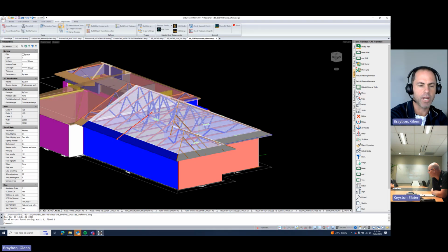Yeah. 100. We are definitely trying to develop the ability of using the light gauge stud section in its strong axis as a beam. Obviously, we're starting with those frame headers. We're doing some testing on that, where we're putting the C90 section in as a wall frame above the opening, and testing that wall frame. It's going to be capped with top plate. It's going to have a sill below it, so it's got extra parts integrated or connected to it that are going to strengthen it, not just relying on that single C90 75 beam section that's been tested.